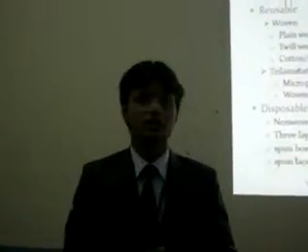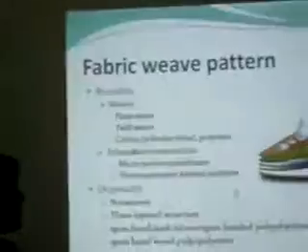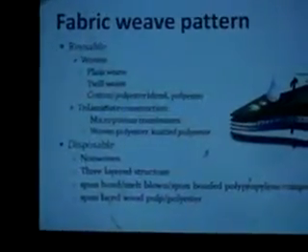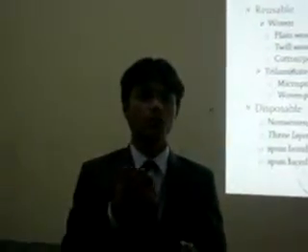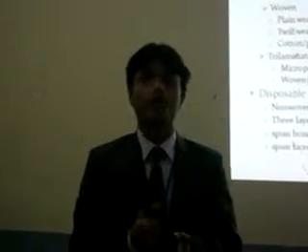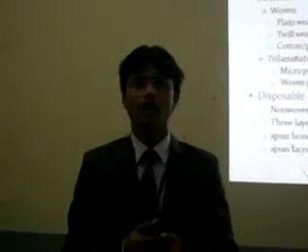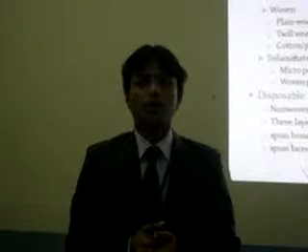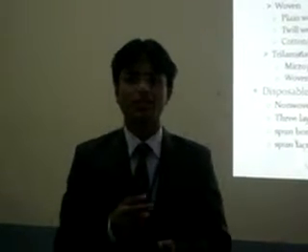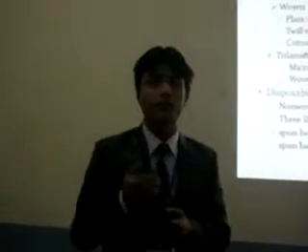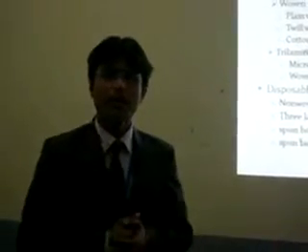While in the case of disposable gowns, non-wovens are used, which are produced directly from fibers or fiber solutions, and the process can be divided into two steps: web formation and bonding. Non-woven fabrics are characterized by fibers more randomly oriented than yarns found in woven fabrics. This successfully increases the potential for the formation of capillaries, thereby reducing liquid transmission.